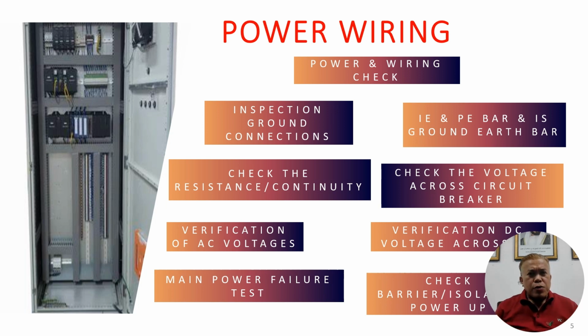So why are we doing power up? In order to confirm that everything is healthy, the connections are correct end to end, and then that's the time we need to see in our HMI or our engineering workstations or in our computer that all is as per graphic, as per logic. So based on the modules and the controllers, everything is healthy. Any gaps should be captured by the punch list.